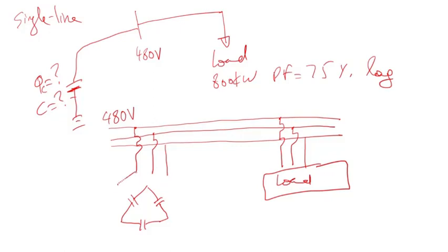I take this back because this is connected delta, so it's not grounded. Anyway, I'm trying to calculate the capacitance and also the reactive power of the capacitor bank that would establish this power factor.